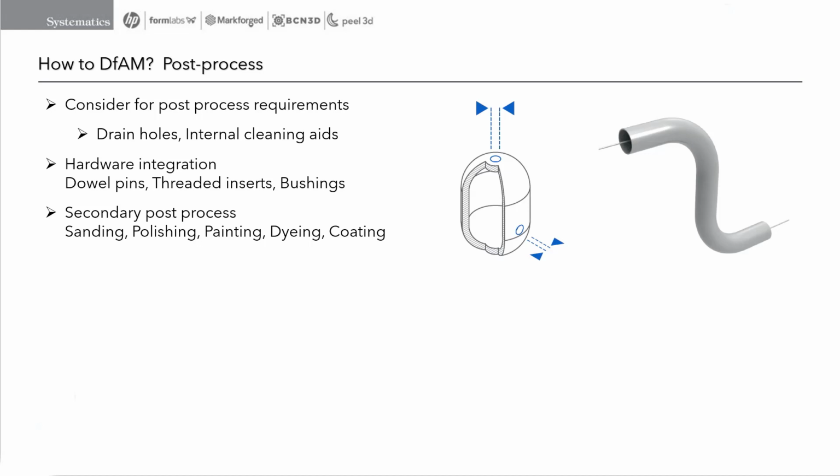The design of the part should be such that it minimizes the retention of excess powder. This can be achieved by incorporating features such as angled surfaces or tapered walls to encourage the powder to flow out of the part more easily.